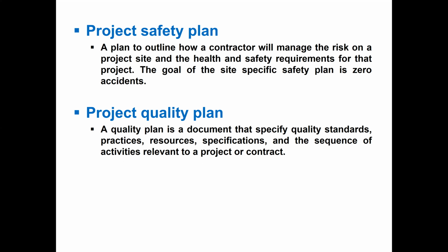And we have to maintain quality and deliver a good quality project. So our quality plan should be submitted and approved by the consultant. As a construction company, we will submit the quality plan on how we are going to ensure that quality on site for the project will be good. So we will make sure of quality assurance, like the documentation, procedures, and the brands when we buy those things, and then do the testing to check if there is a deviation, and how to bring those according to the specifications.